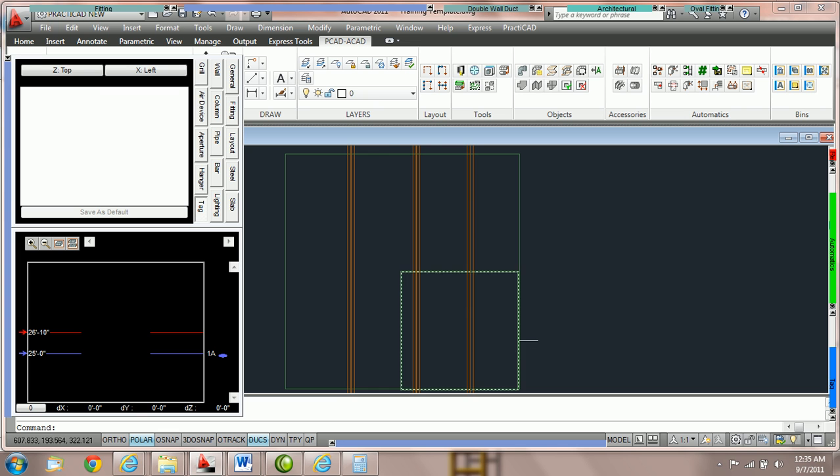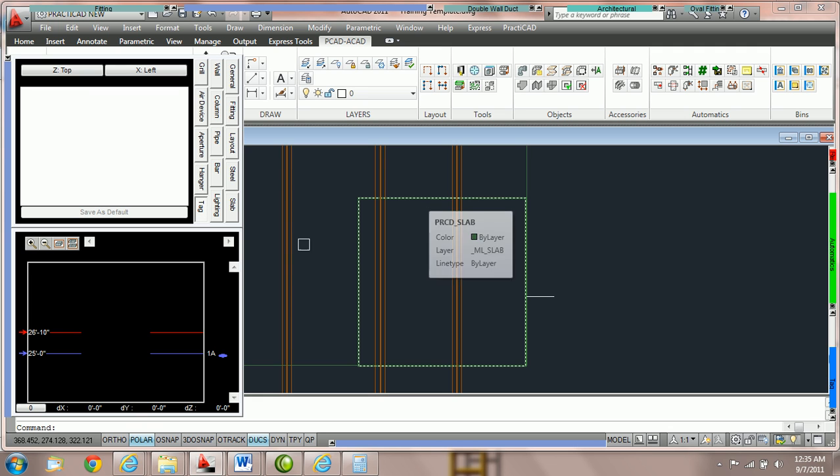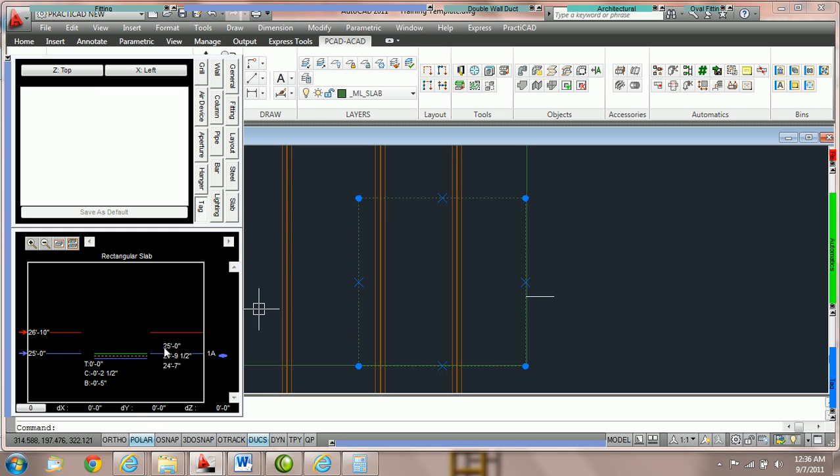In this tutorial, we're going to route duct in this section here. This section we have marked as 1A. And we have set it to be our new relative bottom by just clicking here and setting the bottom to be blue. So we're going to use the top of this slab, which is at, if you click on it, top of slab is at 25 foot in absolute elevation. That's going to be our relative bottom.